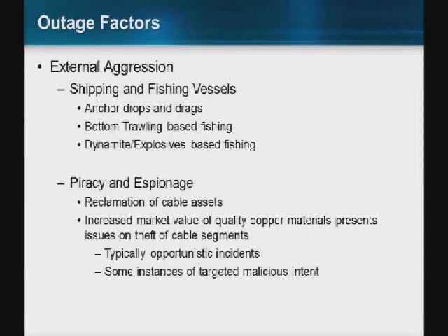So the vast majority of outages are actually not environmental. Most are external aggression. Typically shipping and fishing vessels, anchor drops and drags, bottom trawling based fishing where a net will snag a cable and break it. And to some lesser extent, believe it or not, dynamite and explosives based fishing. There are portions of South Asia where this is unfortunately commonly practiced. It's kind of cheating for fishing, but it does do damage to cables.